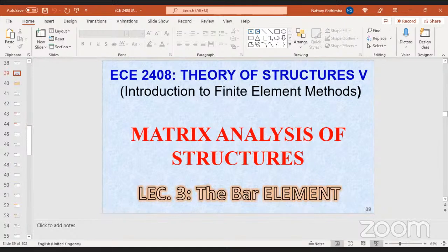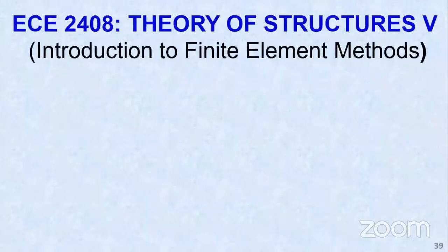So today we go ahead and look at what we call the bar element. Now, in essence, what we were calling the spring element in real life situations will not have springs, but we said it's a very useful instructive tool because it behaved in a way that we could employ the basic fundamental equation, that is F equals K delta, without having so many variables, because it can only carry axial load. So today we are handling the same trend, but now we go to a real finite element.